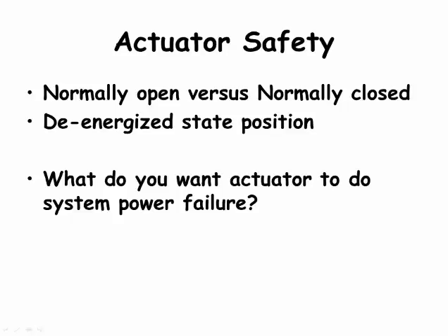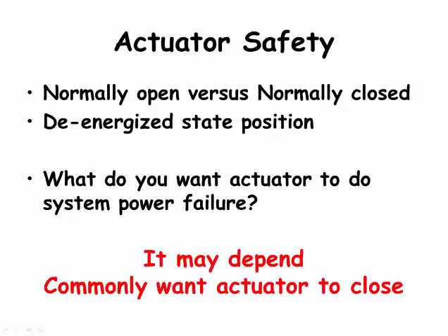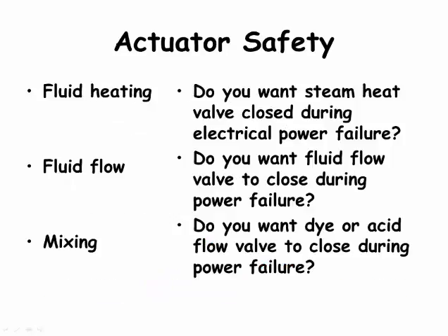This question is relevant mainly to solenoid valves. Do you want the valve to be open and allow flow when there is a power failure, or do you want the valve to be closed? It may depend, but in many cases, people want the actuator to be closed. When thinking about this, think about flows and impacts both downstream of the actuator and upstream of the actuator.